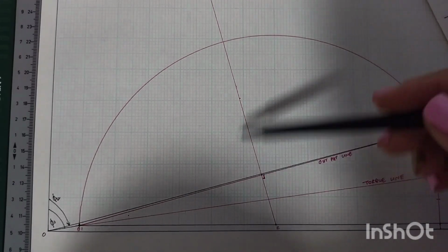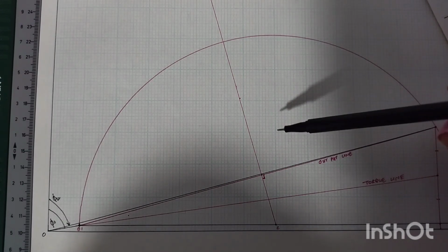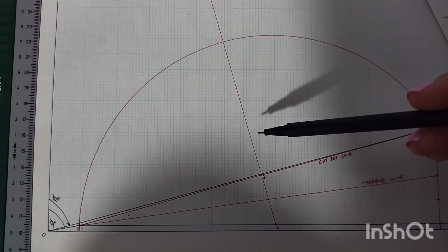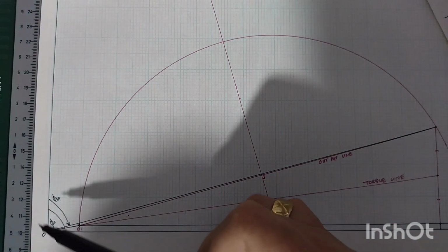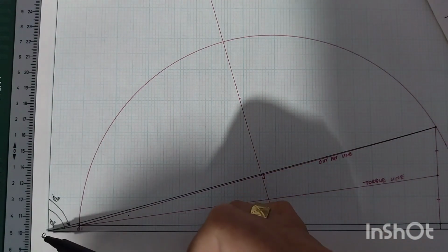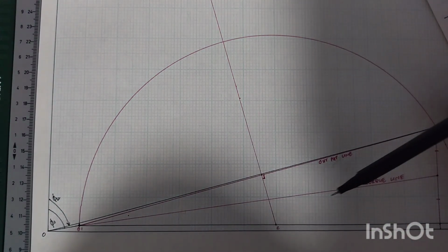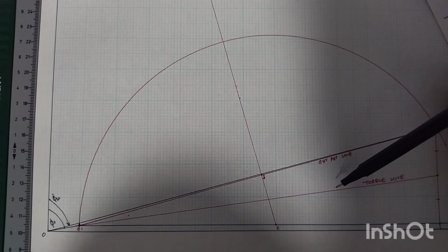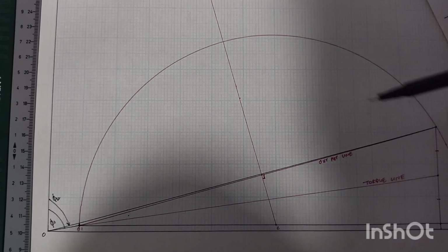So by now you've figured out that the perimeter of your circle gives you the various loads. So there are three conditions which you might be asked to obtain information for. The first one is full load. I'm going to do all three on this circle diagram. So the first one I'm going to construct is your full load line. I'm also going to construct the line for max output and also for maximum torque.